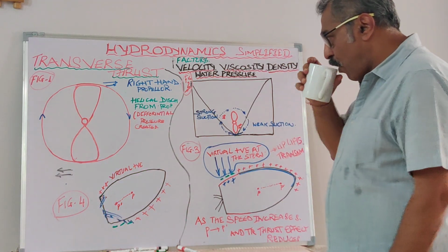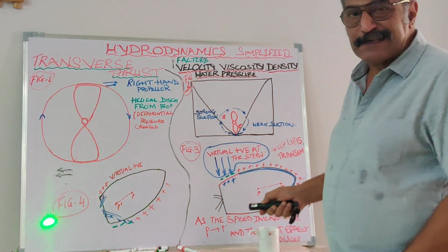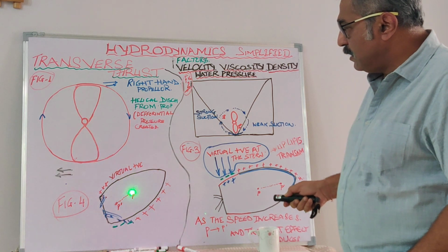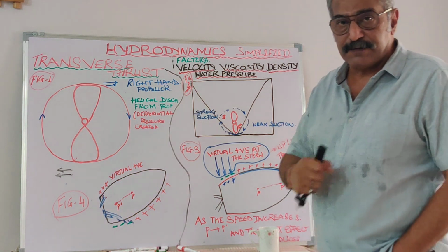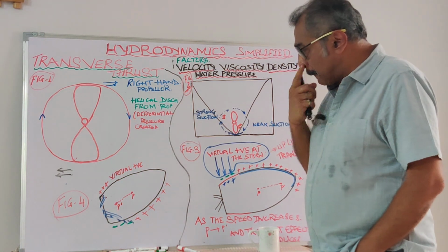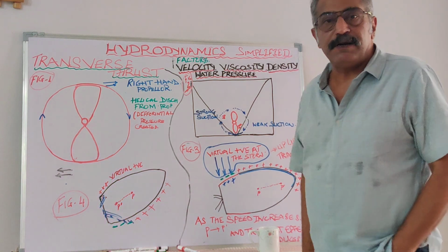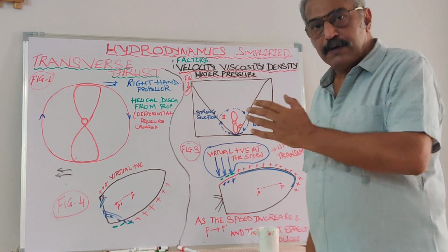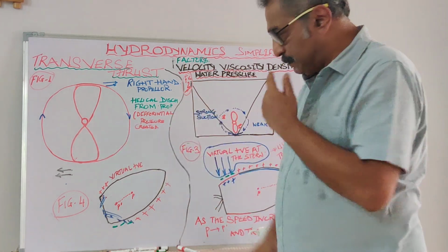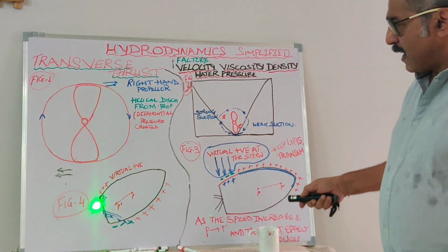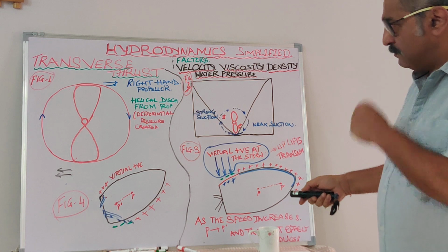Now coming to figure number 4. When the vessel is going astern, initially when the vessel is at rest, the pivot point is at the center. But the moment the engines are given stern, the pivot point will go up to L/8 and then will settle approximately at L/4 because of the water pressure generated for the ship. When she is drawing astern, the water is moving forward, the ship is going astern. On a right hand screw, the bow will cant to starboard as per the property.